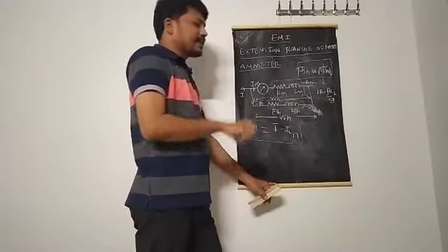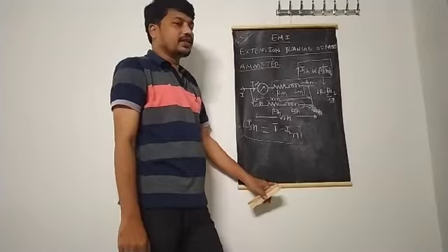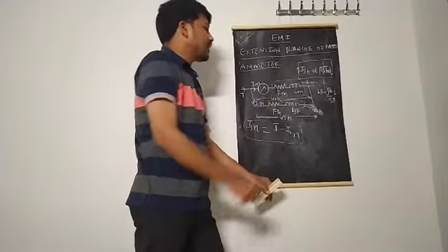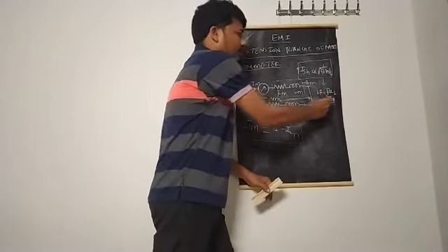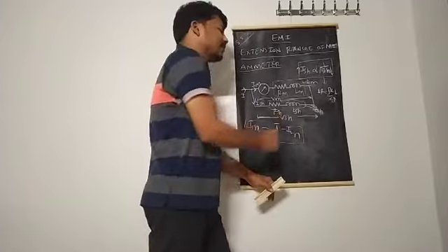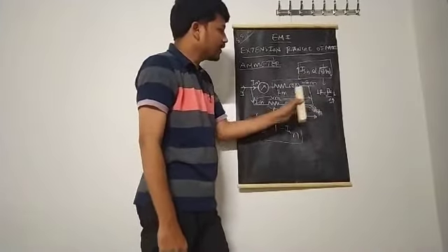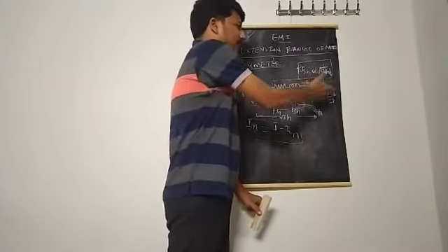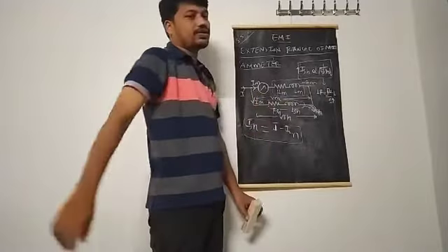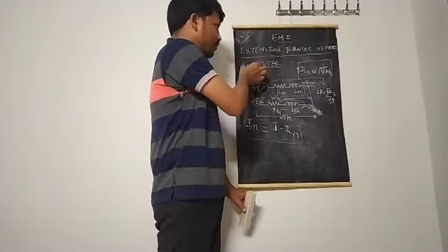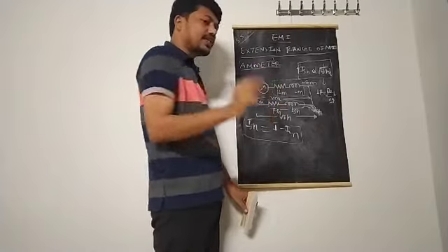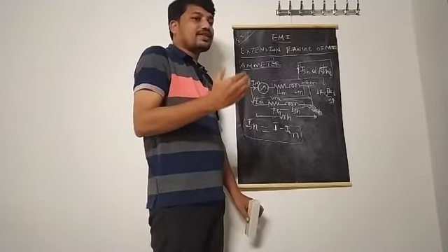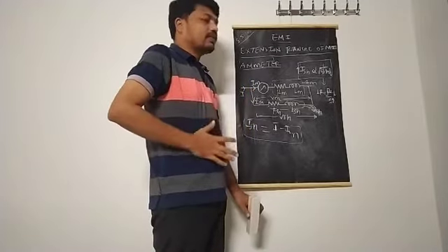That means in case of extending the moving iron ammeter, the resistance we want to connect should be low resistance and having a very thick wire. Because area is more with a very thick wire, and length is very small, the resistance is very low. Low resistance, thick wire, and small length. It should be a less number of turns. So to extend the moving iron ammeter, the shunt resistance should be low, the area should be more, that means thick wire, and fewer number of turns, and the length of the material should be low.